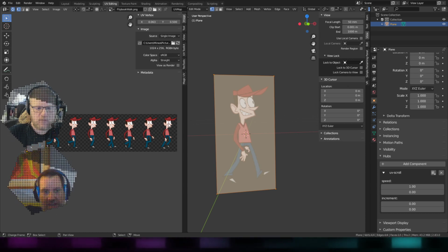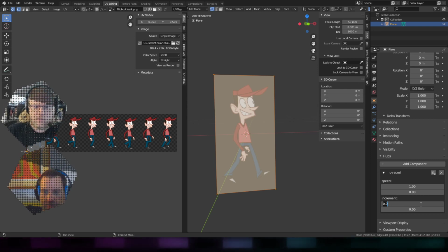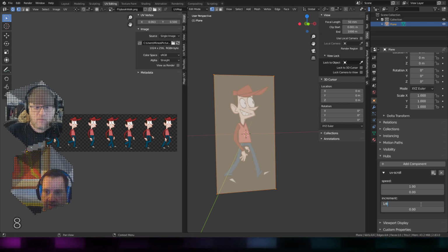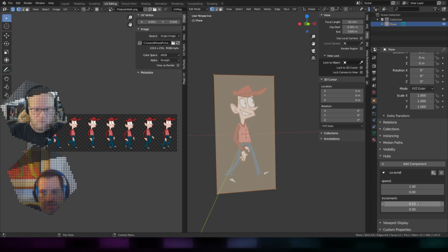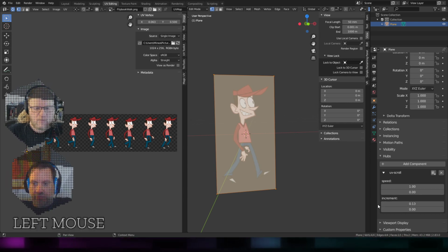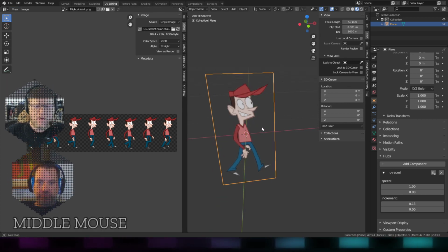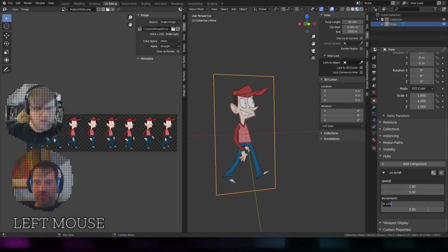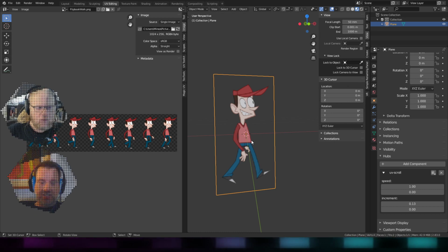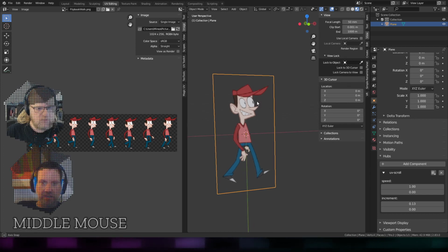So I need 1/8. The nice thing about Blender is you can go over to this as if you were going to type a number and instead type 1 divided by 8, enter, and that's the number I need. It's 0.125, but it's rounding it to 0.13. I think it might even just be showing the rounded number. Yeah, when I click on it, it says 0.125. That's good to know when you look in the UV scroll example, because it says 1.3. It might be confusing.